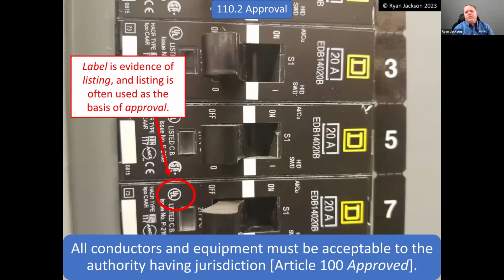Okay, so the authority having jurisdiction is the NFPA's term for what the I codes would normally call the code official, right? So the authority having jurisdiction is the person or the people that are responsible for enforcing the code. And this section says, listen, everything has to be acceptable to the authority having jurisdiction. So how do I know that these breakers are going to be acceptable then? Well, probably the easiest thing to do is to check if it's listed.